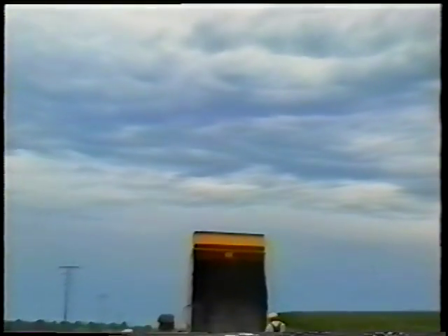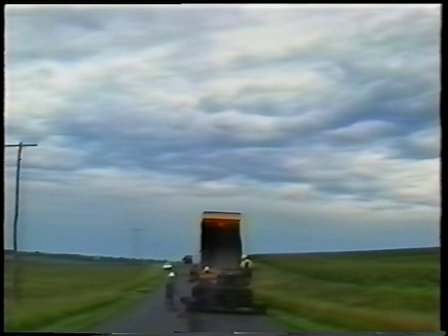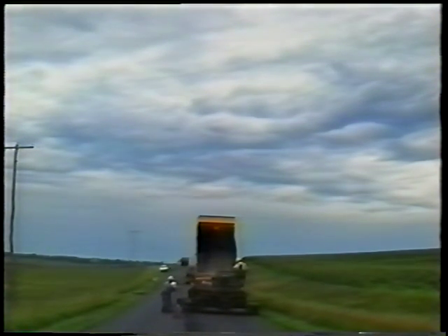Precipitation is a concern. Asphalt paving should not begin when rain is about to fall or too soon after it's fallen while the surface is still wet. Occasional sprinkles or passing showers have to be dealt with according to their volume and duration, from working right on through the minor ones to temporarily halting for the more serious ones.